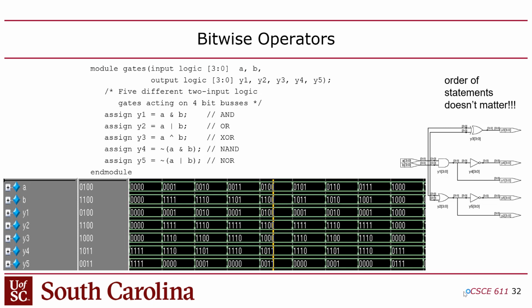And what's even crazier about that still is in C++, you put the rows and then the columns. But here, if you're putting the width and the depth, it's reversed. So not only are the bracket positions weird, but they actually switch logically the dimensions of the 2D array in Verilog with respect to C or Java. But anyway, yeah, we'll get to that.